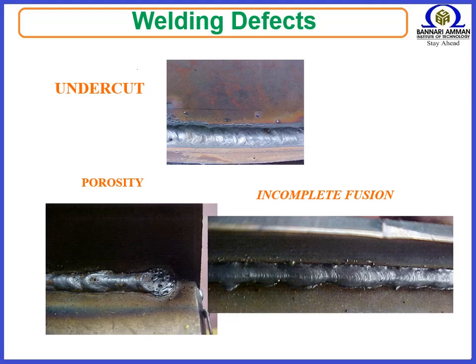It can be caused by the use of the incorrect welding process or wrong welding technique. So below we'll learn about the 7 most common welding defects, their types, causes, and remedies. Undercut. This welding imperfection is the groove formation at the weld toe, reducing the cross-sectional thickness of the base metal. The result is the weakened weld and workpiece.